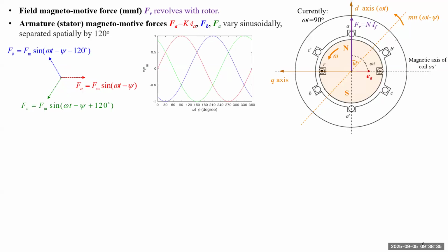As I said, we then need to measure the lengths of each magnetic force. We draw the 3 winding currents, then multiply by K, which gives the actual value of the magnetic force. So each one will be a sinusoidal function. Another thing to know: the picture shown is only for the moment when the voltage in winding A reaches a maximum value.